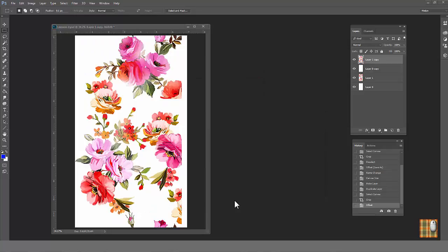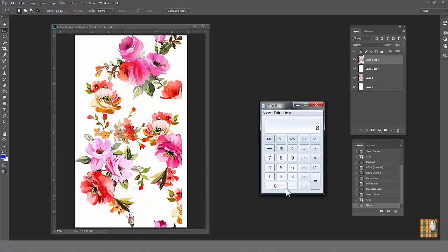One more hint. Here is another reason to use 200 dpi. It's the easiest resolution for calculation. Length 12 inches, offset is 1200 pixels. If length is 17 inches, offset is 1700 pixels. But you can use the same formula for any resolution.